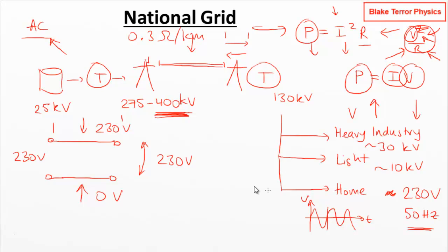So for one floor in the house, say you're downstairs, or say you've just got a flat, you'll have one wire which goes all the way around the flat, which is our live cable. We'll have another one which is the neutral, which goes all the way around. And every time there's a plug socket, we're putting in an ability to plug in some kind of device between these two cables. So this will be our plug socket with two of the pins. We have 3 pins on a plug in the UK. I'll get onto that in a minute.